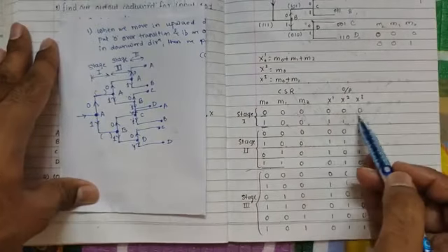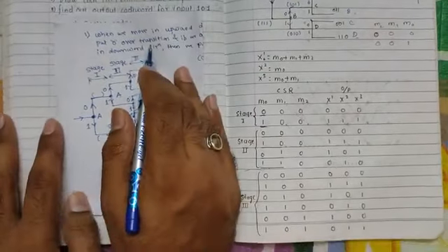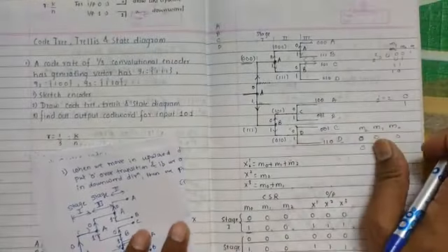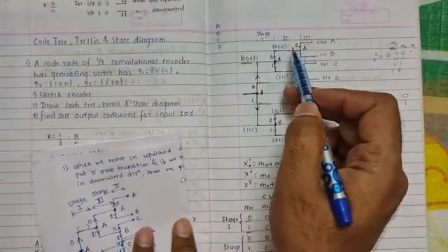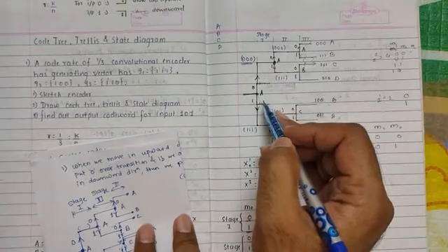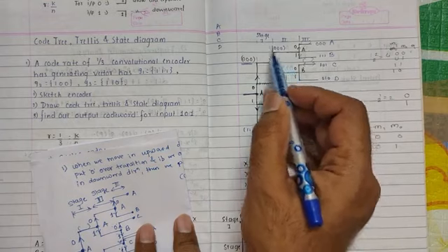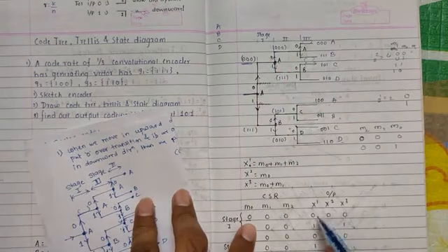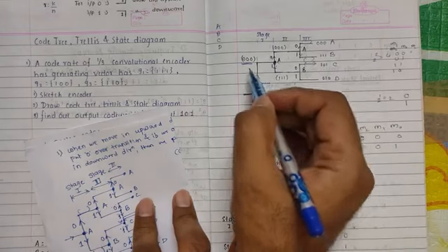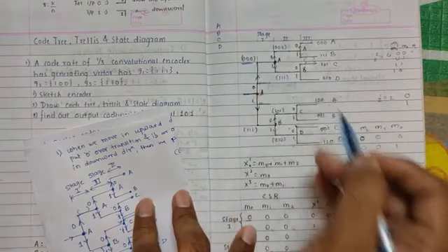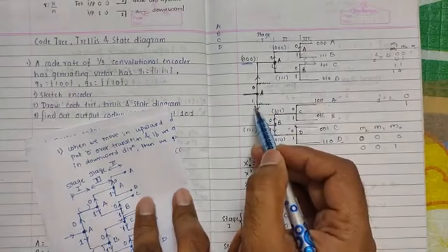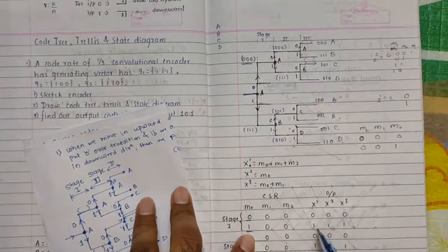Now we'll have to write this output on this tree diagram. I have drawn here this tree diagram. So if you see stage 1, stage 2, stage 3. Now when we are moving from node A to A in the stage 1, it is because of this input 0, and what will be the output? It is 0 0 0. So that's why I have written 0 0 0. And when we are moving in the downward direction, it is because of input 1. So for that I have written the output 1 1 1.